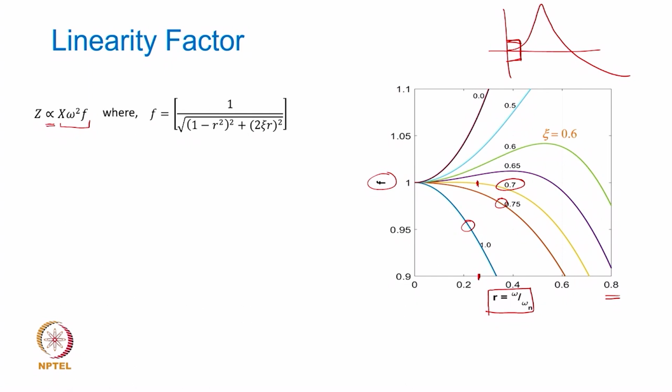You see that, which actually means that f is not going to really matter in the proportionality here. Okay. If f is equal to 1 for a certain frequency range, now I am talking about this frequency range 0 to 0.25, this f is going to be 1, and then you can always say that whatever the charge output that you are getting from an accelerometer is going to be proportional to the acceleration, right, directly proportional, and without any multiple. Of course, there will be omega n square that has to be accounted for, but that is not going to change the behavior as such.